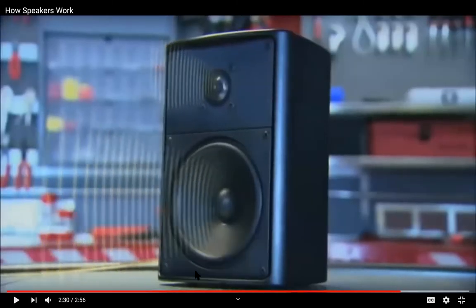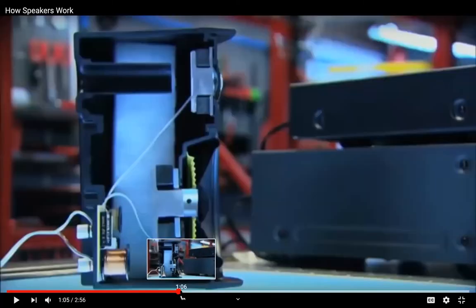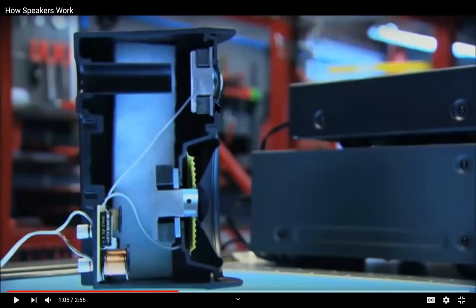So one of the things that goes on inside a speaker, and then we'll show this here, there's this device down here called a crossover. What the crossover does is filter so that the big speaker doesn't get the high frequency and the little speaker doesn't get the low frequency. That way you can direct the big speaker to do more work in the bottom frequencies and have the little speaker do more work in the high end, right? So that's basically the nutshell of a multiple speaker system.